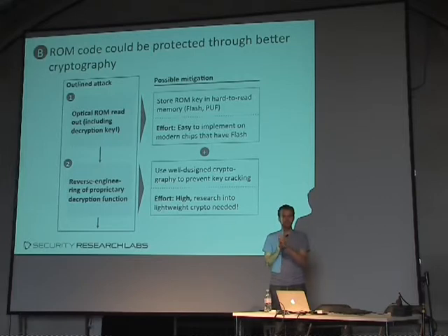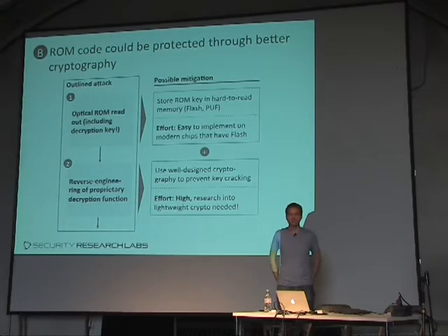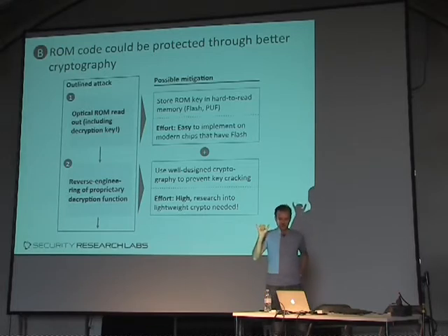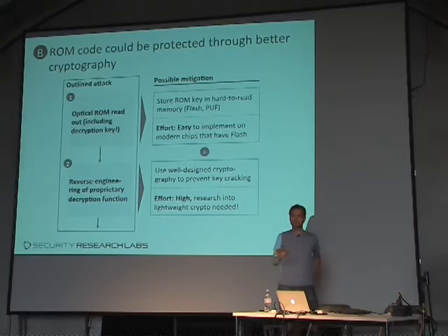that the key is stored in the ROM is, of course, stupid. Why store the key next to what you're encrypting? I mean, who would do that in any other application? But on smart cards, you don't have many places to store it. But there's one much more secure alternative, that is the flash or EEPROM memory. Right? So by just storing this one 64-bit value in flash, or make that 128-bit to be a little future-proof. So spend 128 bits of flash, and these devices have something like 72 kilobytes of flash.